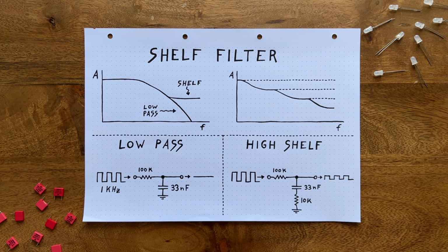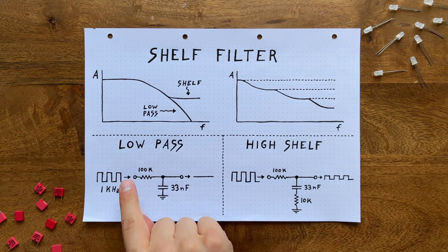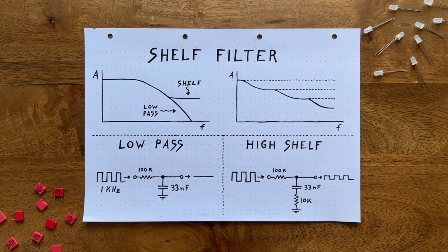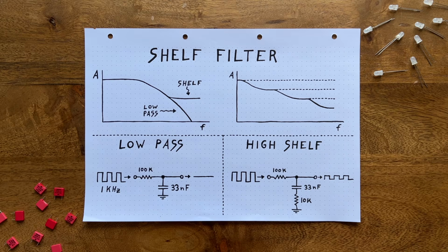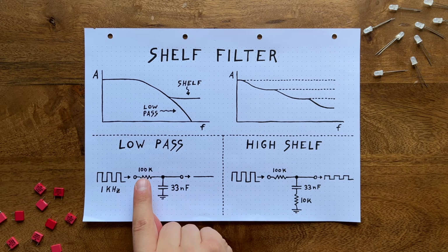Hence the resistor comparison. With this in mind, this structure essentially becomes a voltage divider. And in a voltage divider, the output voltage depends on the relation between its 2 resistors. The weaker the resistor going to ground is compared to the other one, the lower the output voltage will be. And in our scenario here, the capacitor's resistance is extremely low, because it's almost empty. Which is why the voltage above it stays close to 0 volts. And it never goes beyond that, because during the input signal's low phase, the tiny amount of current we pushed into the cap gets pulled out again.